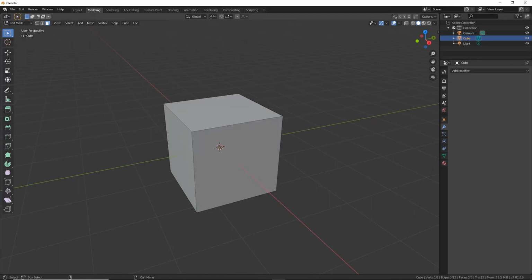Now I can also multiple select, so if I hold down shift you'll see that I now selected 2 at once, and if I click on it again while holding shift I'll deselect it, and that works for my vertices too. See how I'm selecting them like this? And the reason that it's important to do it is because it means we can move things around, as well as rotating them and scaling them obviously.